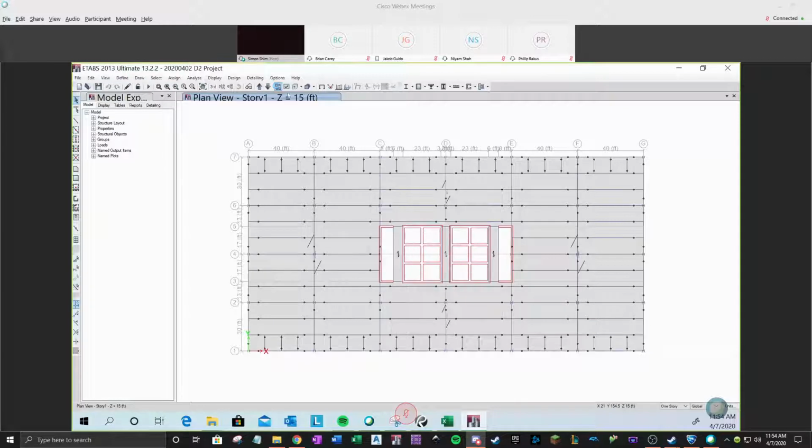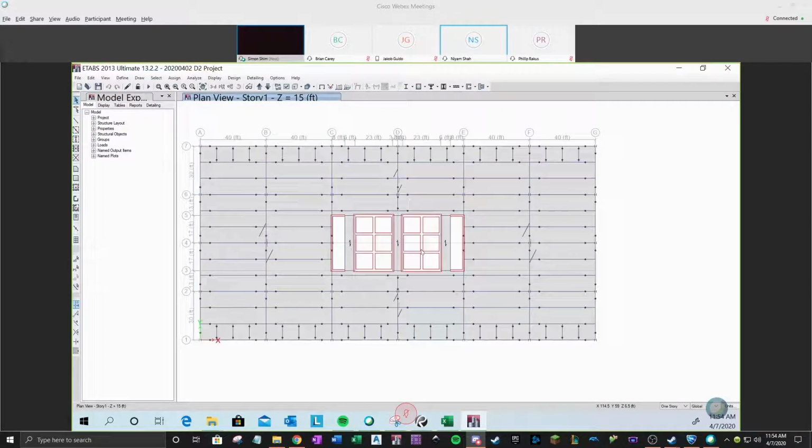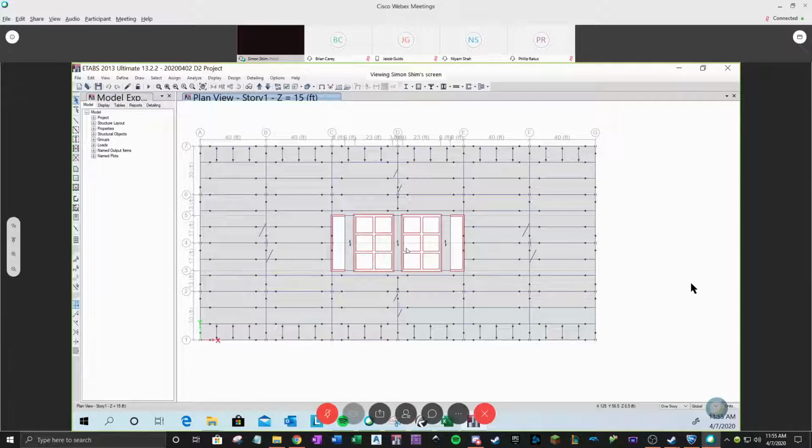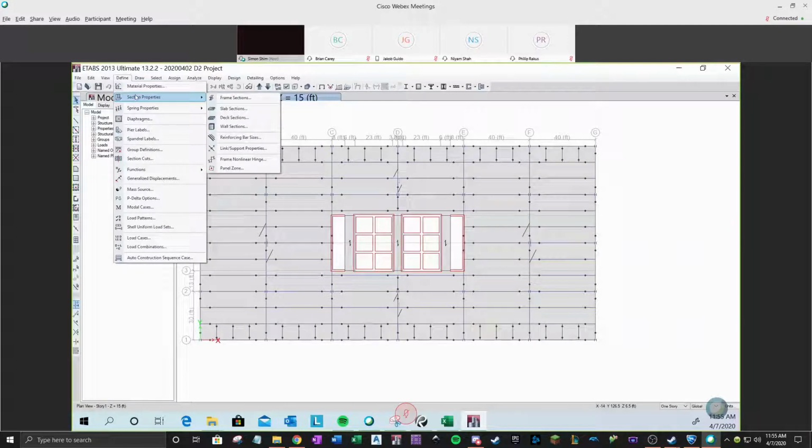The spanning direction is correct. Okay, now another question. For the corridor walkways, that's also going to be 4,000 psi lightweight concrete, right? Okay, there is another thing: likely these slab elements are not, I think this is something you need to understand as background. Not always the case, but in this case, our slab is not a secondary element, not even the lateral system. We only treat it as gravity floor framing, so we don't need a high strength concrete. Since we're using 4,000 concrete for the metal deck, I think 4,000 for this 1 inch slab makes sense.